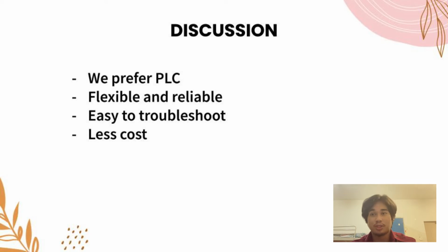This obviously makes the troubleshooting process easier, by just reconstructing the ladder diagram. Since the PLC uses a CPU program, it is really easy to upload and download the required logic. Furthermore, it also consumes less cost, because in the olden days, relay-based systems were very expensive in the long run, since we use many wires and we need extra tools just to manage and arrange the wires. So PLCs were designed to replace the relay-based system, and a PLC purchase is like a one-time investment which reduces money consumption during troubleshooting and maintenance. Hence, this is the reason why we prefer PLC control systems compared to relay-based control systems.